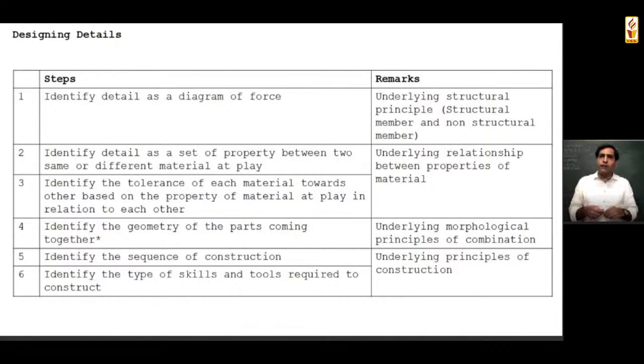Okay. These are the rules. If you want to follow, it will be easier. Identify detail as a diagram of force. So for you, I have made this model. If you look at this model, I have diagrammed this force. Now I have to apply the force perpendicularly. So if I am applying the force, I have to figure out whether this member is in compression or tension.